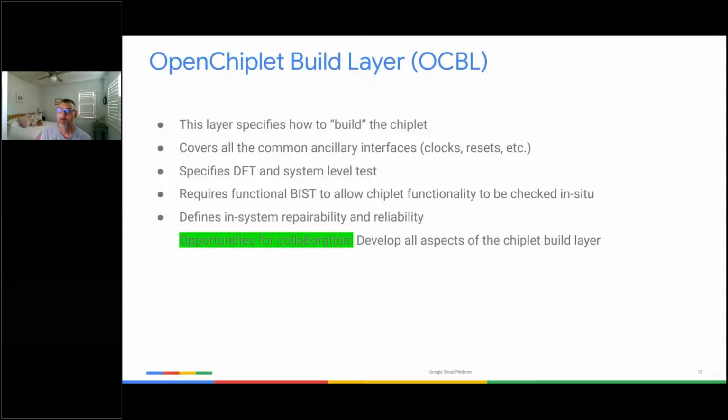The other method is memory BIST, where we can run and test all the memories in the system. We can do incremental repair in the system if a bit fails two years down the road. You can map in spare bits and self-healing structures.